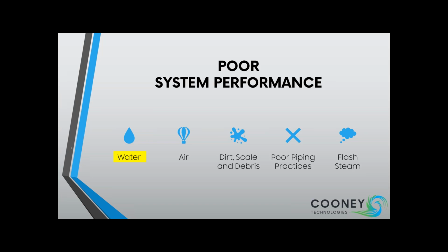It could lead to really poor heat transfer and could possibly cause some dangerous water hammer. This is caused by different things, usually undersized piping on a steam main or a condensate main, or an undersized drip leg diameter that can cause that pesky water hammer. It could be a blockage in pipe strainers before your traps that doesn't permit the condensate to flow through easily. And because of excessive back pressure in the condensate piping, that doesn't allow the proper flow of condensate. Check the size and look for possible back pressures inside the receiver vent line.